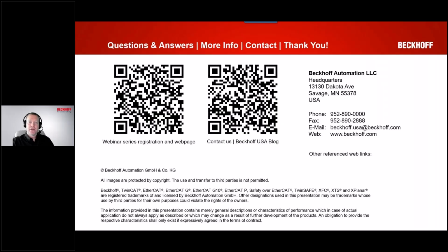We moved to servo drives that had built-in safe motion, and it ended up moving some of these components, the contactors and feedback side of things, from the safety into the component itself. It's kind of the same idea, where we're going to move everything into that module, for example the servo drive, and handle safety in there.